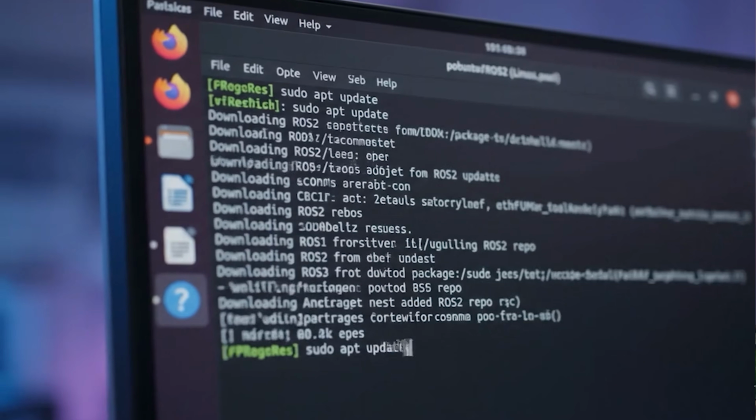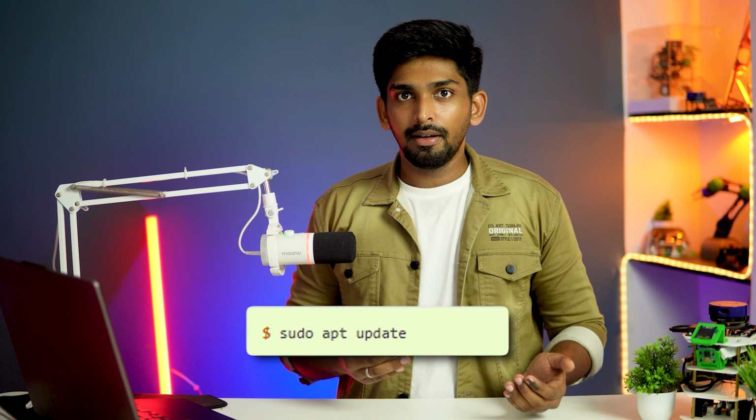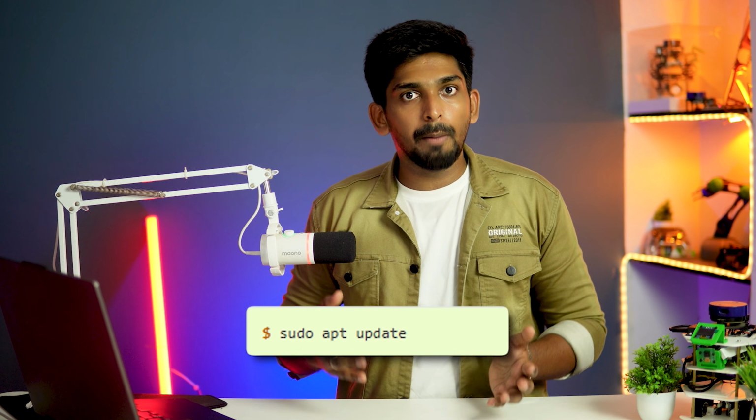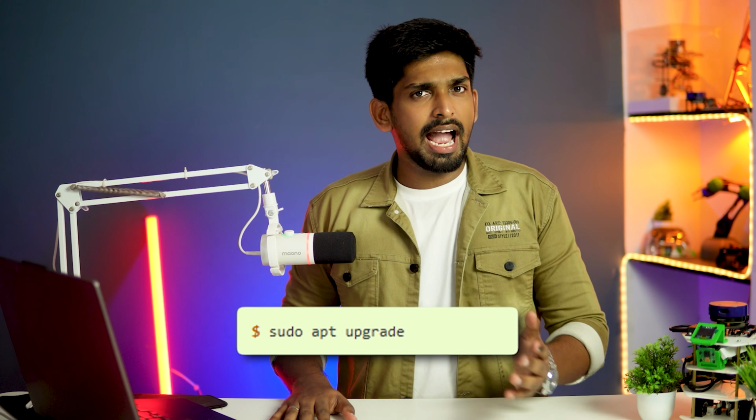Then the optional but strongly recommended block: your build system plus additional utilities for writing and compiling ROS2 packages. You don't need dev tools to run ROS2, but you need them to build everything. Install them now. Refresh the package list. Now it includes the ROS2 repository you just added. Upgrade, bring all your existing packages up to date before we install new ones. Okay, now the actual install.